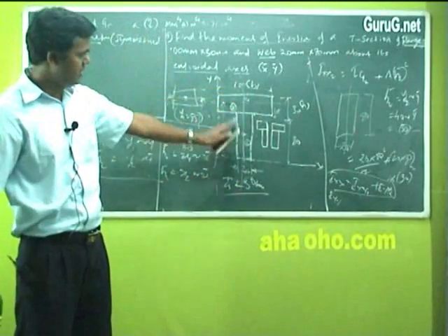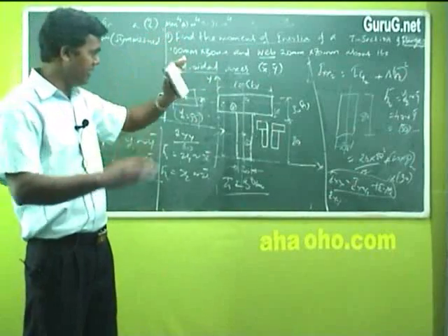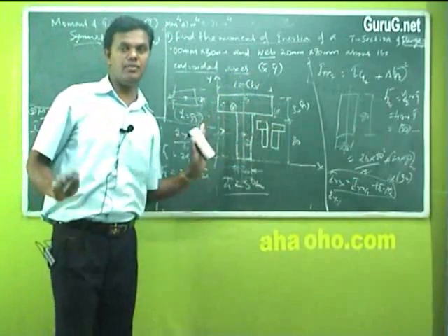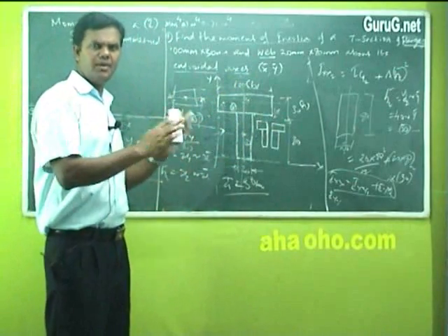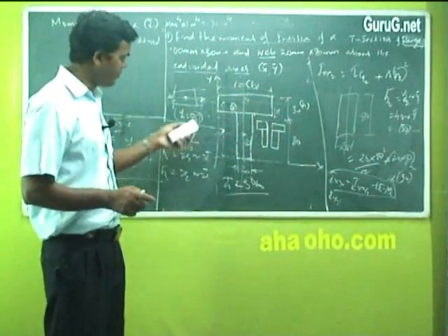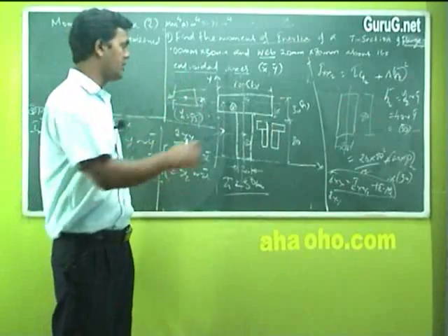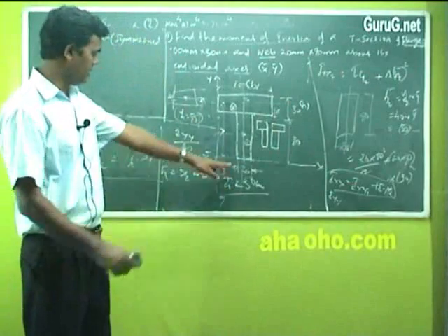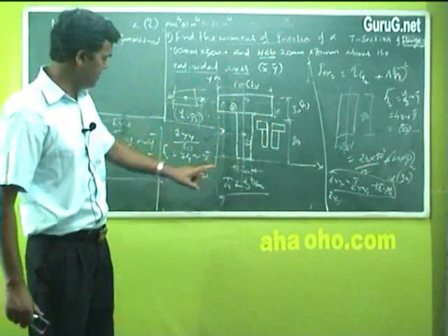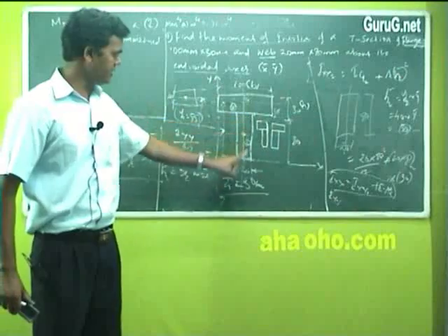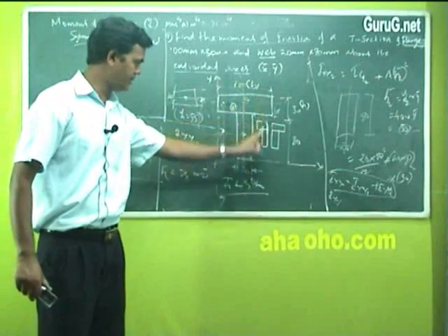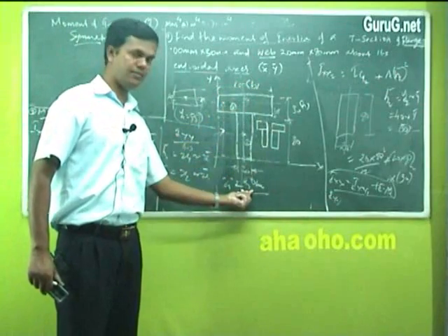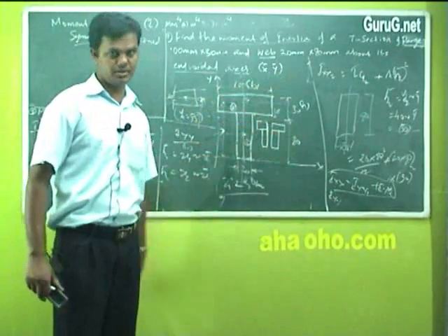By the sketch, if it is symmetry about any axis, you can directly tell its X bar value is half of that total value, because it's half, the symmetry. Suppose it is symmetry about y axis, you can directly write the value of y bar there. So here your work is easy because x bar value is directly written as symmetry, total by 2, since it's 100 by 2 is 50. Even if you solve it, you get the same answer.